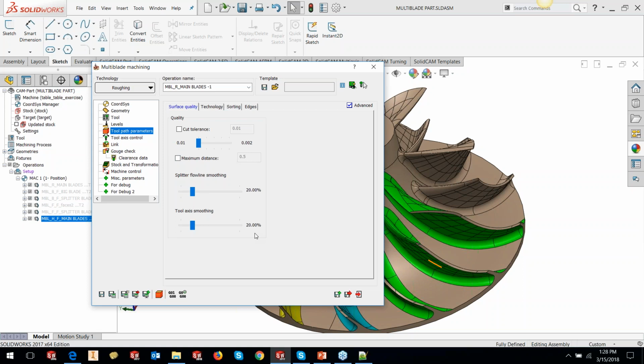For example, the tool is coming to the end at this point, and then from this point, the tool is just sticking to the end and rotating around with the part in just the C-axis. There's no change in A or B, but the C-axis is just rotating. If you see such a movement happening quite often in your roughing or finishing toolpaths, the culprit is here in the tool axis smoothing.